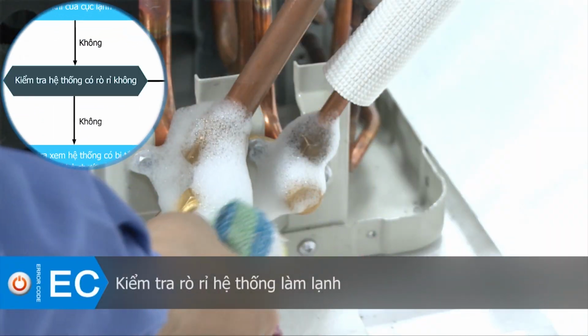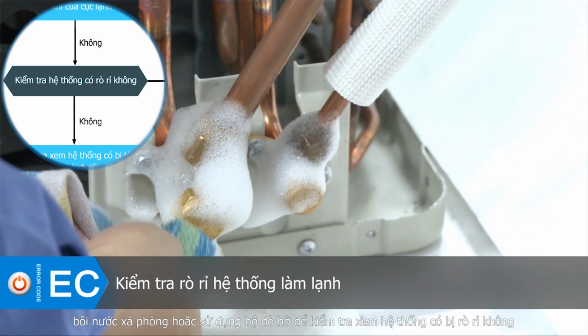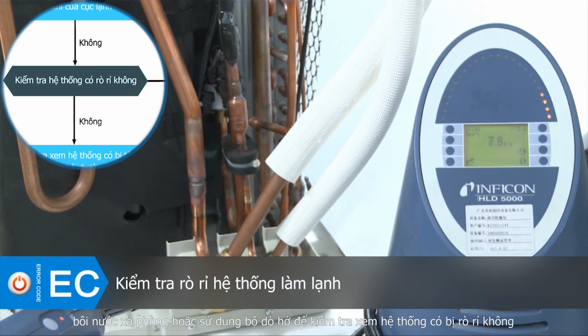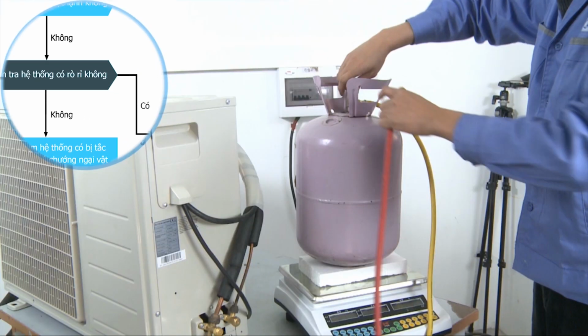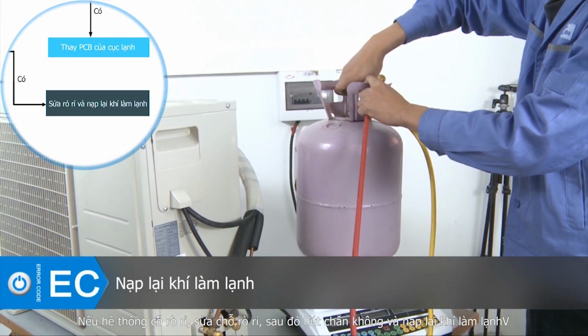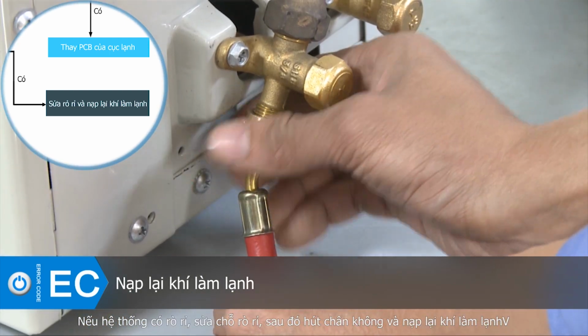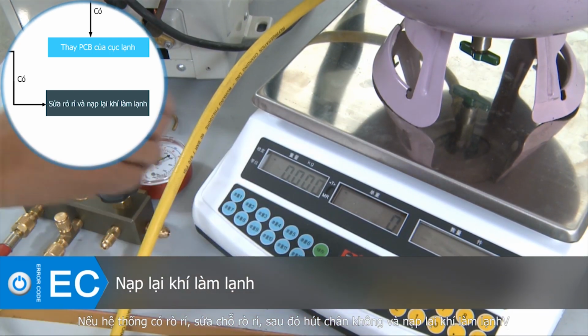If there is refrigerant oil on the joint, apply soapy water or leak detector to check if the system has any leakage. If there is any leakage in the system, repair the leakage. Then vacuum and recharge the refrigerant.